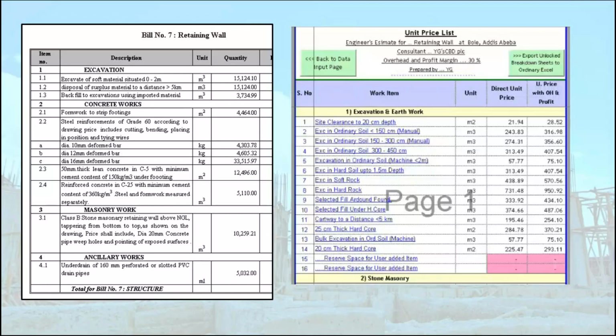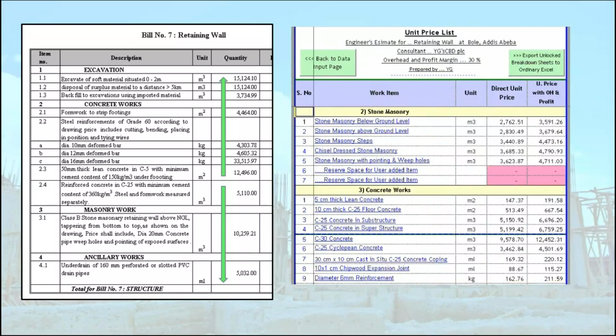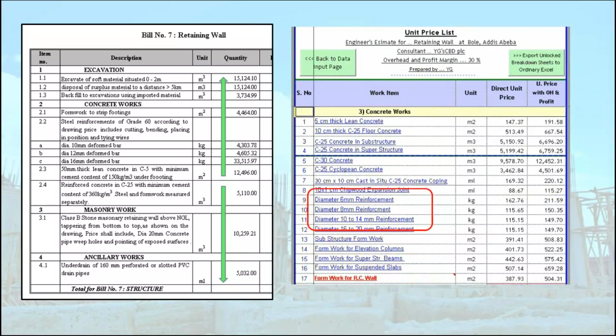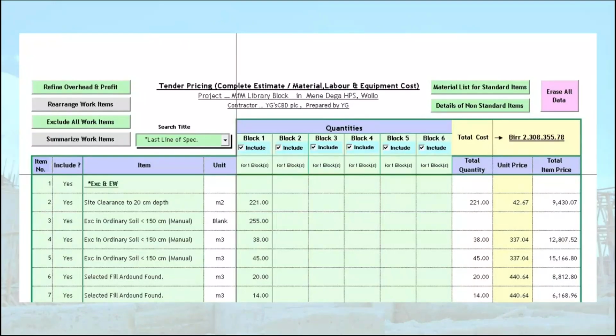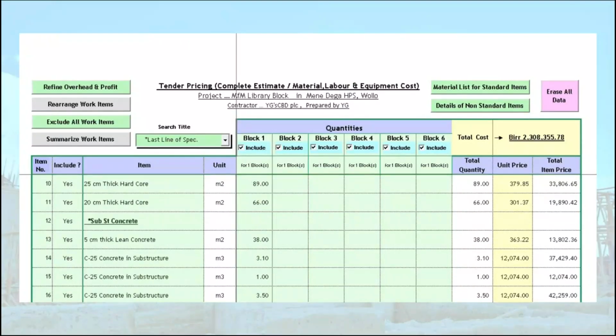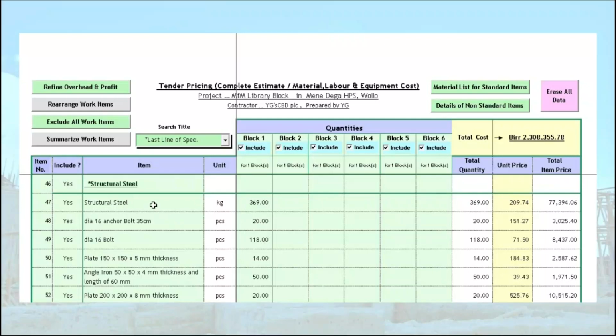As a general rule, civil work projects like our retaining wall example involve a small number of work items with large costs and thus can easily be handled by selecting work items and their unit rates from the standard unit price list. However, when we are dealing with a building project, the number of items in the BOQ will considerably increase, and preparing a standard cost breakdown page for each one will become time-consuming and inefficient.